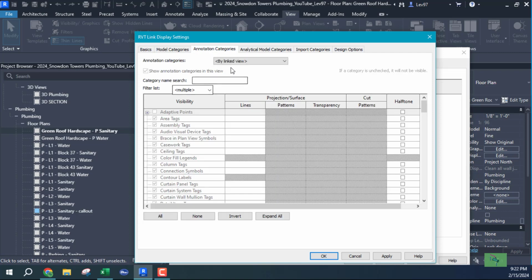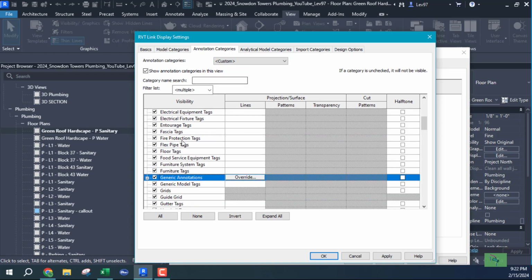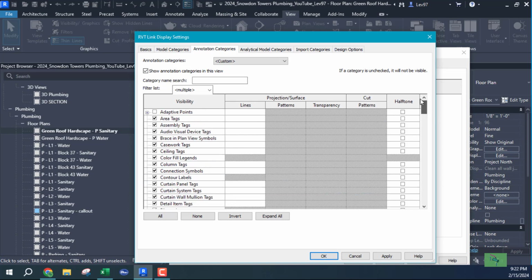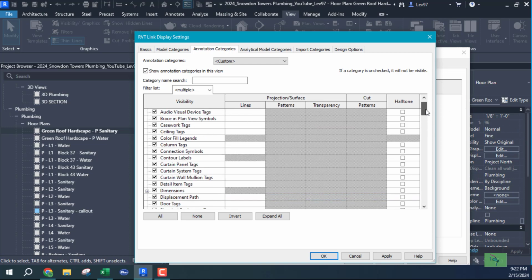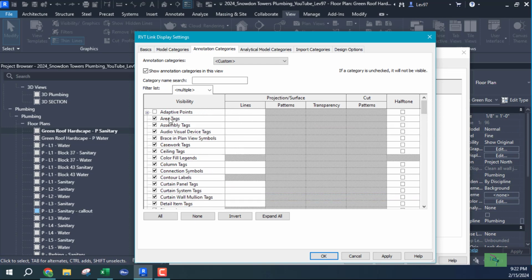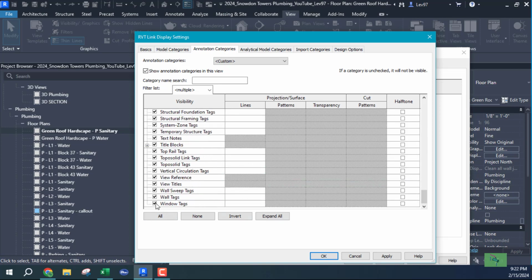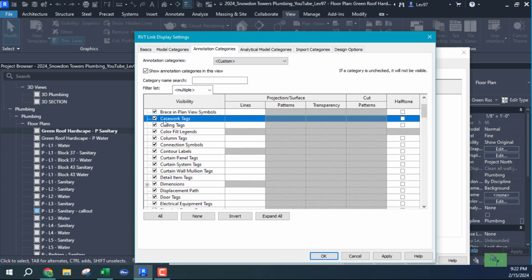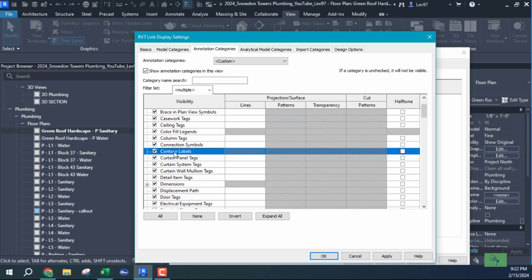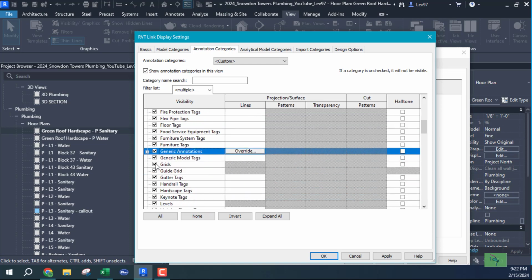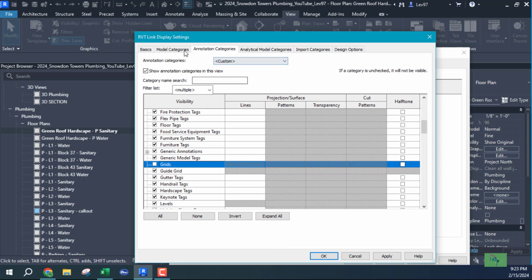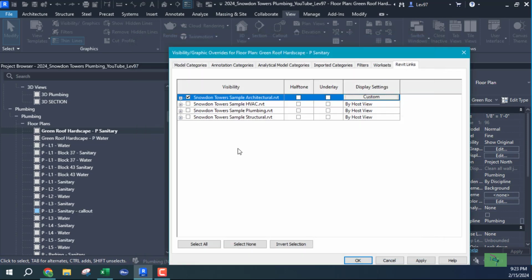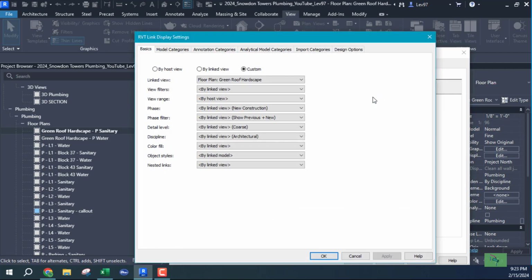And for one, it's going to be that grid. I need to turn that off. So you go here, right? Let me go back again so you guys can get this. You just click here and type G, or you can go up and type S or T or whatever. If I want walls, I don't have to look here, move my mouse all the way over, come down to wall, right? I can go here and type C for ceiling, but what do I want? I want G. So we type G, we're going to turn the architect's grids off. We have the architect's grids off, and we are custom.